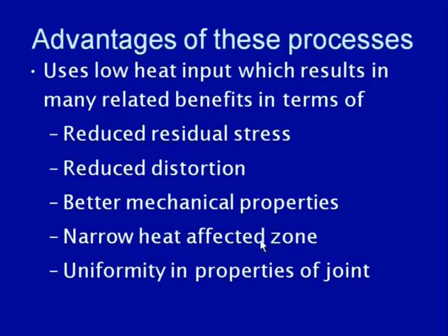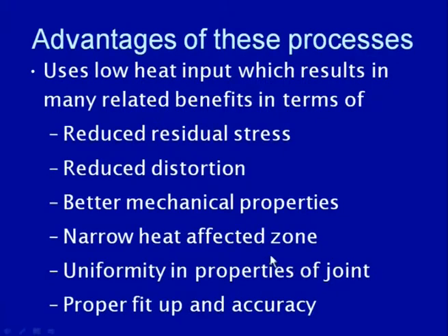And the next is uniformity in properties. The narrower the heat affected zone, the better the mechanical properties in the base material, which results in greater uniformity in the properties of the joint which is formed, but the strength of these joints is further limited by the properties of the filler material.